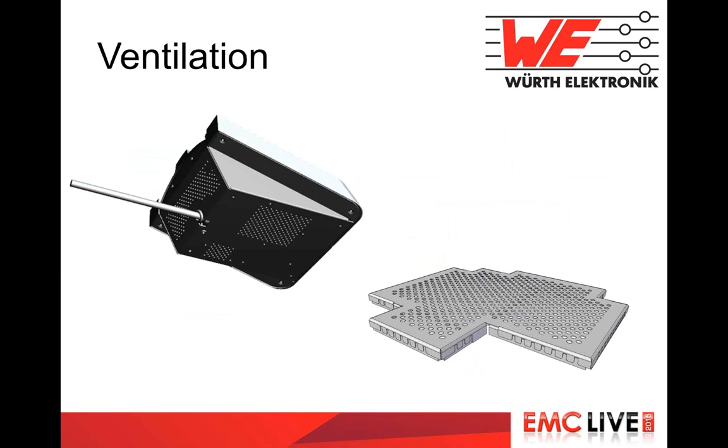So we will go to the next group of discontinuities, ventilation. Ventilation is always needed to some degree when we work with electronics. Currents are flowing through resistances and some electromagnetic energy is converted into heat. So we need to provide some ventilation, and how can we do it without creating discontinuities in our shield? Well, I think probably we can't. What we can do is minimize the effect of these discontinuities.